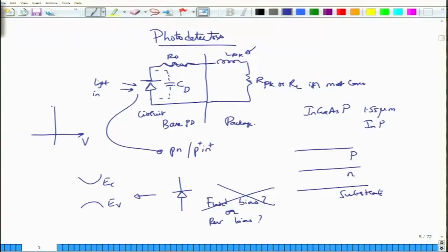But now when you apply light, there is a good chance that these carriers will be recombining, okay. Even before you apply light, because of the forward bias, a large amount of current is flowing. So, if you look at the current to voltage characteristic of a photodiode, you would see that just a small amount of bias is sufficient for a large current to flow through. And when you launch optical signals, instead of optical power being absorbed, you actually start getting more optical power, okay, and because it is depleting, the current would actually reduce.